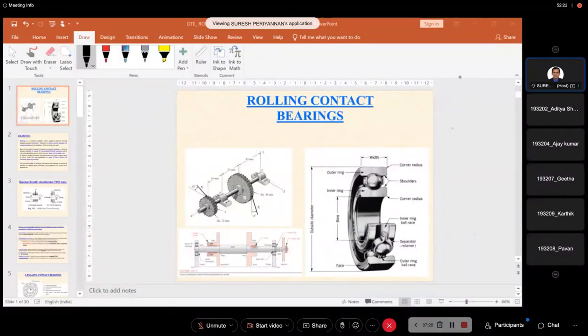In the thick film, hydrodynamic lubrication, we concentrated mostly. Thin film lubrication is like metal to metal contact or boundary contact. Later we discussed Petroff's equation, and the coefficient of friction generated between the inner bearing surface and the journal surface, using Petroff's concept.